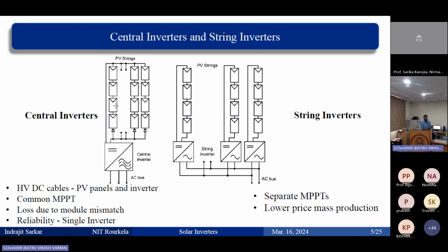But reliability, it is like we have a three-phase system and a single-phase system. If it is a three-phase system, let's say in a hostel, 3 floors are supplied from 3 phases. So if one phase is gone, then the other 2 floors will get power. But when it is a single-phase supply to all the 3 floors, if that phase is faulty, then all the floors will not get power. The same issue you are going to have with the single central inverter.